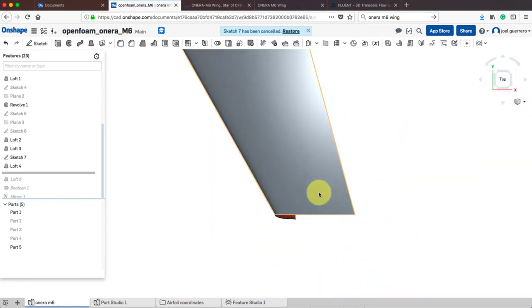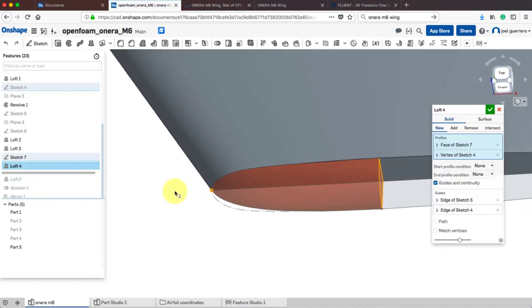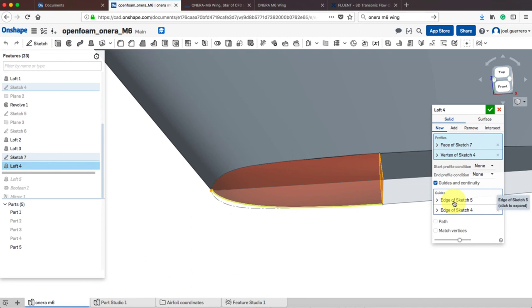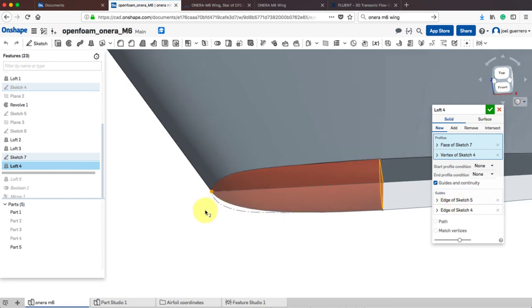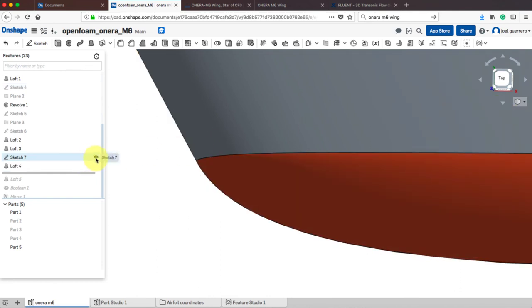I know here I have a different loft line. So if I click here, see that I have this edge and a second edge. Okay, so see that I'm following exactly this edge, which is perfect for me. But then to avoid the problem as we have in the revolve, I created a second edge, which doesn't have that tangency here. You see that it goes normal to this face. In this case, I created a spline and I try to make it continuous here, following the tangency.